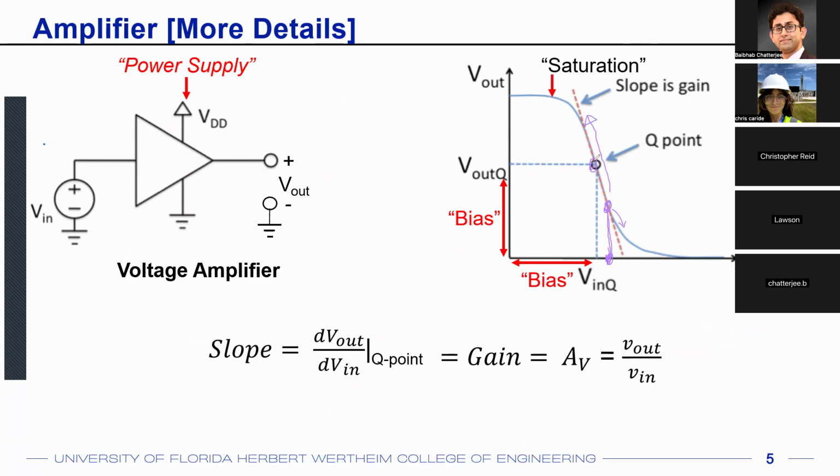So that's why I said to try to be at the middle of your VTC. In that way, you'll have almost equal regions of voltages to use on the top and the bottom of the VTC. That gives you the maximum amount of linearity, which will be clear when you see some examples.